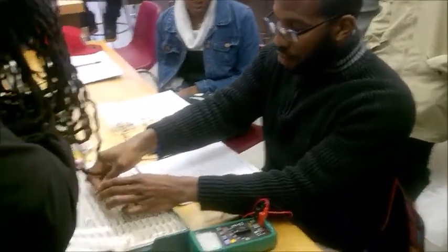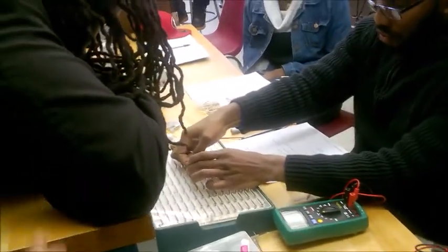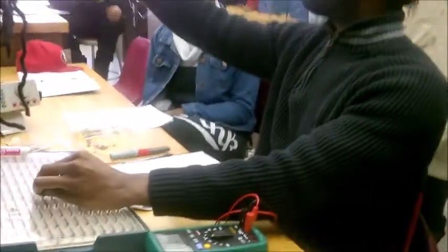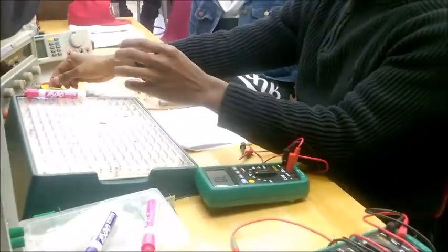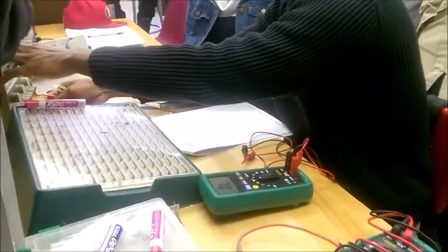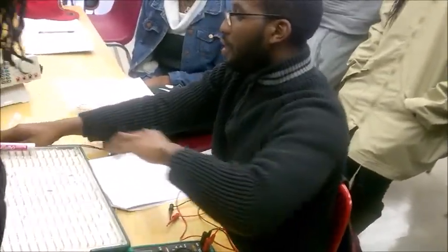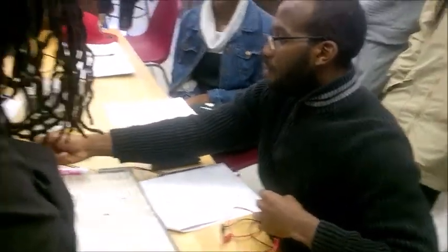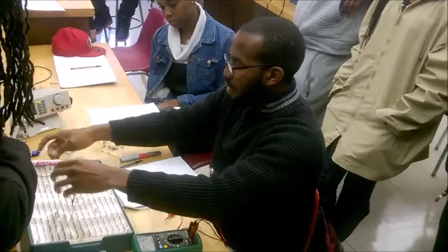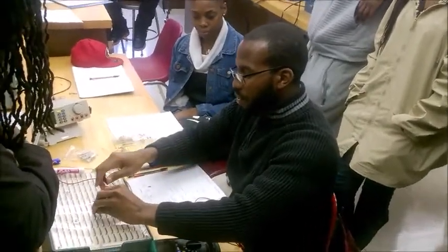So again, the circuit is very simple. We are told to construct this circuit here. And like we saw on the board, the only thing we have is the power supply and the meter. So here, instead of using the fixed power supply, we're going to be using the adjustable power supply. Negative is here, positive is here. First thing we do is to turn it on. Make sure that the current is up and the voltage is down to 0. So the positive goes to the resistor here. The negative goes on this side to the resistor as well.